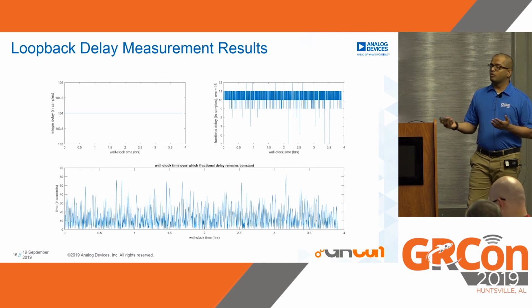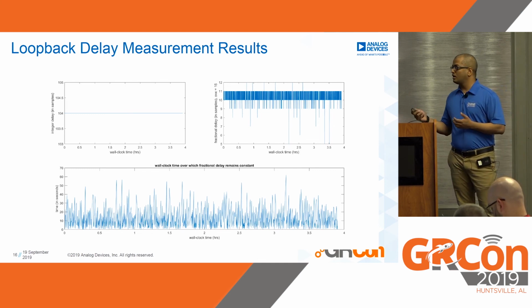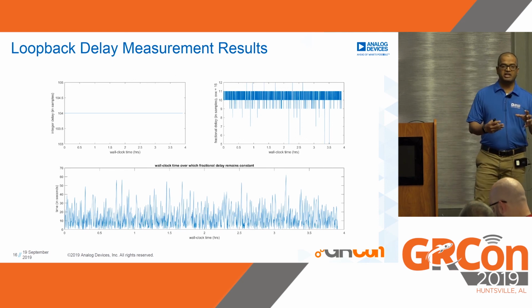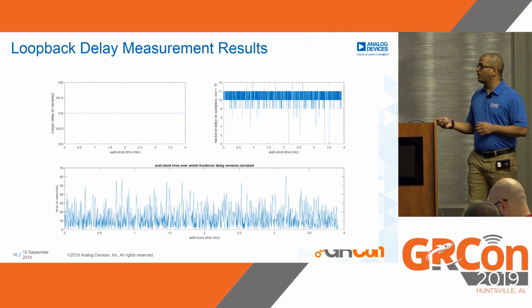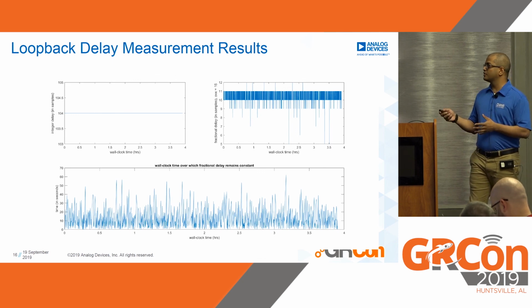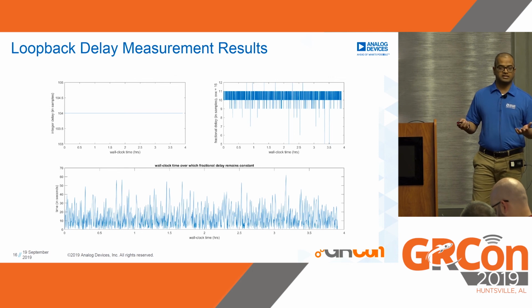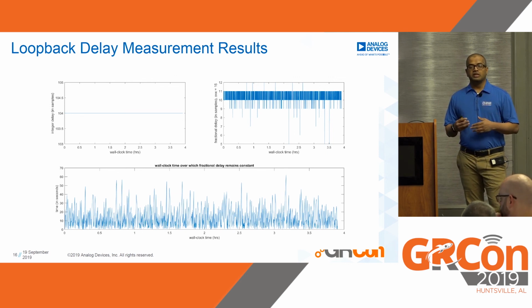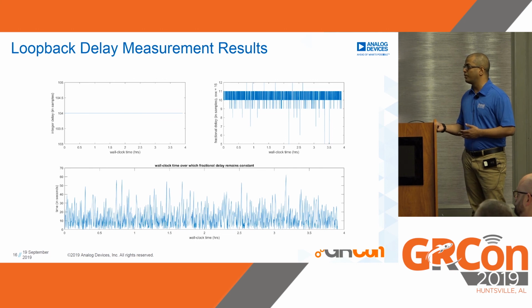What that means, tying this back to the DPD task, is that this is the time scale over which the DPD needs to adapt its coefficients, because the behavior of the chip itself in terms of introducing some delay has changed over that time scale, which is of the order of seconds. And it is significantly longer compared to the number of samples that we might process or the number of packets that are received for a real-world standards compliant waveform. So this tells us that the DPD algorithm needs to adapt over a time scale spanning seconds. That's the conclusion that we got from this plot.